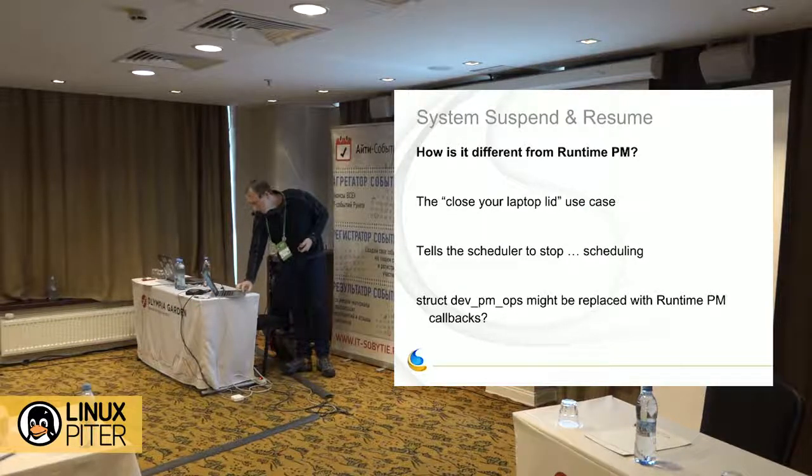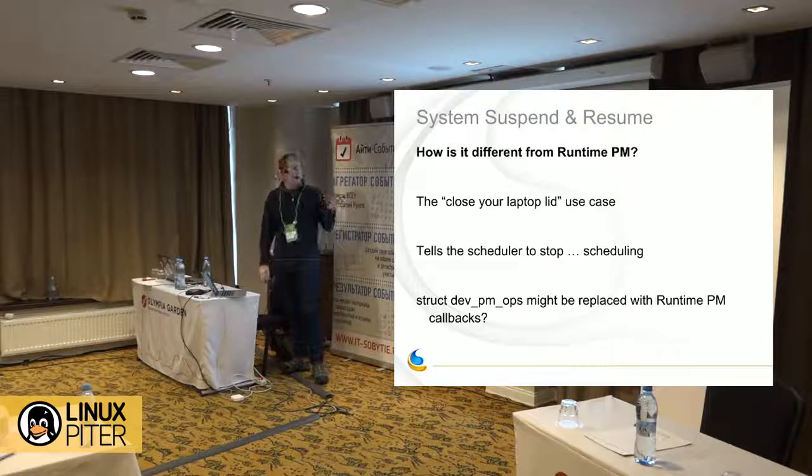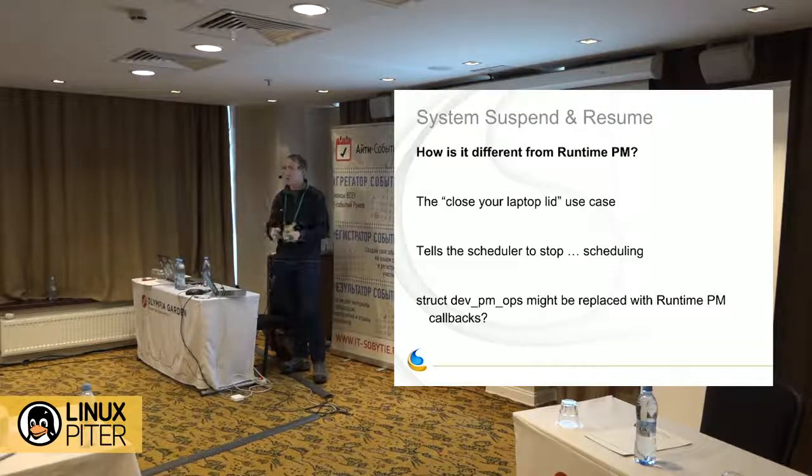All right, so yeah, we're making good progress here. So what is system suspend and resume, right? Because system suspend and resume has been around for a long time, and I haven't talked about it yet. So how is it different than runtime PM? Well, the best example I can give is, runtime PM is this fine-grained kind of thing where you're trying to save power on all the different modules on the chip, right? I mean, you have device drivers that map usually one-to-one onto these modules inside of the SoC.